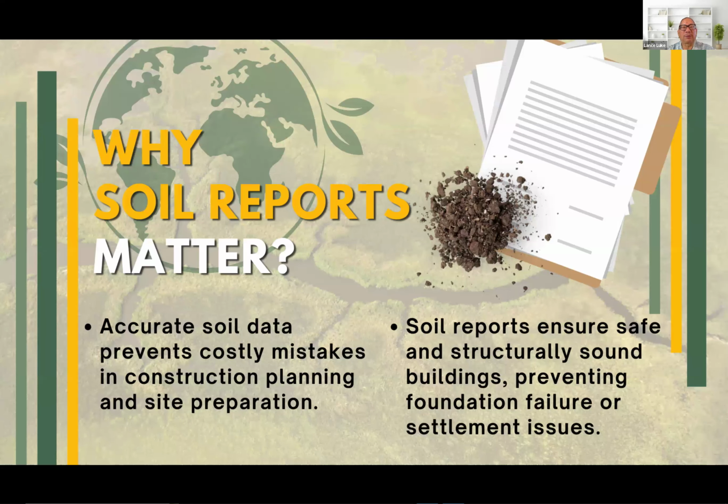So why do soil reports matter anyway? Accurate soil data prevents costly mistakes in construction planning and site preparation. Soil reports ensure safe and structurally sound buildings, preventing foundation failure or settlement issues. Now, there are times where you may hear talk about foundation cracking or settling and those kinds of things. That may be due to the soil condition.